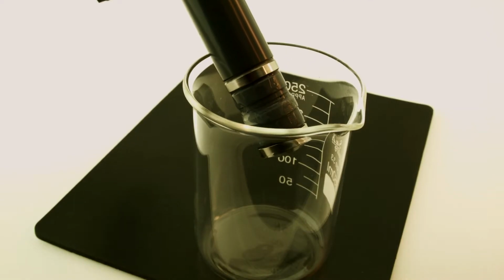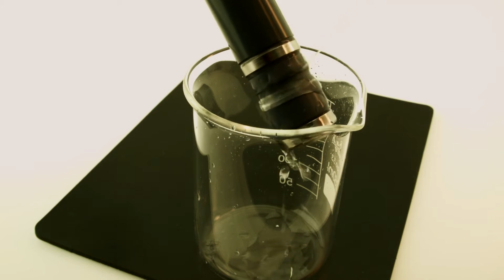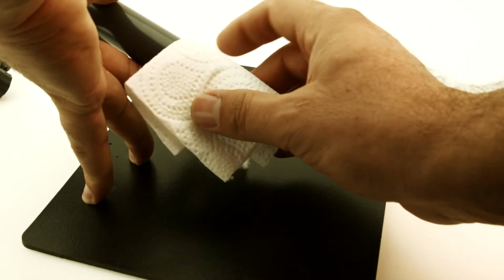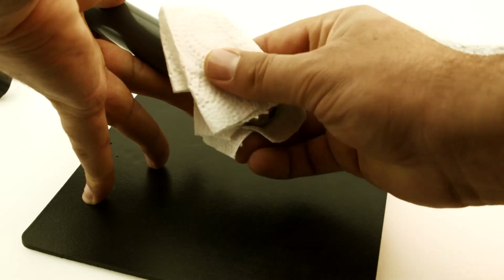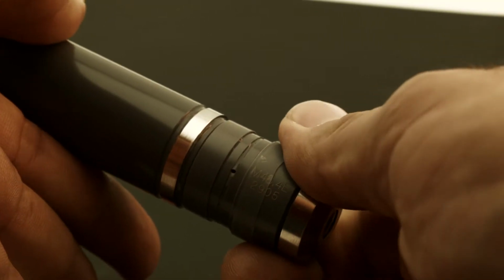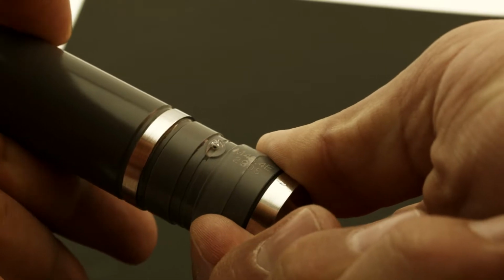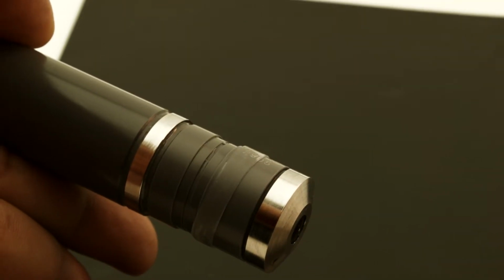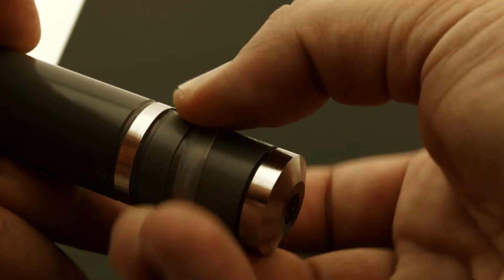Rinse off any excess electrolyte that escapes from the top of the cap and through the vents, and then dry the probe exterior. Now be certain the membrane cap has been hand tightened as far as it will go. Finally, slide the elastic seal into the slotted position over the vent hole, making sure that the seal is seated correctly and not twisted.